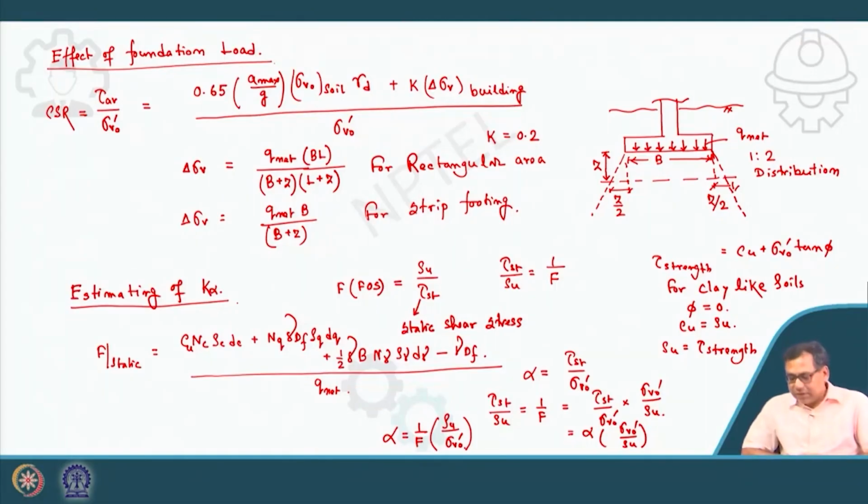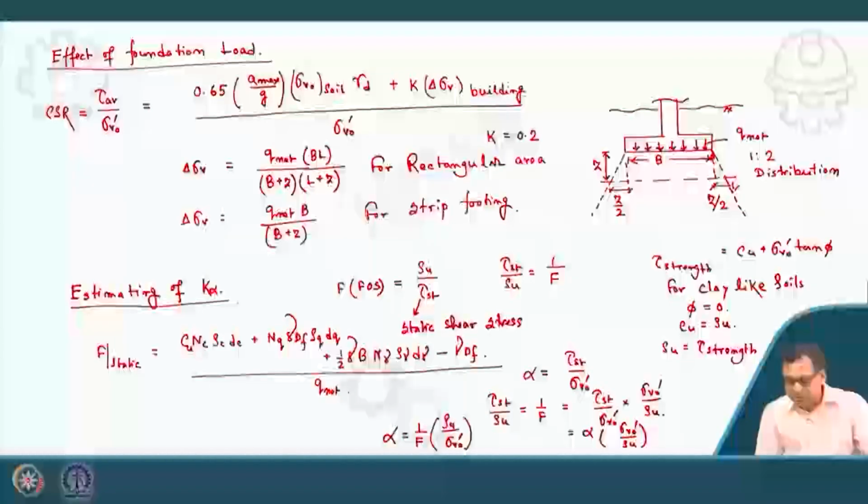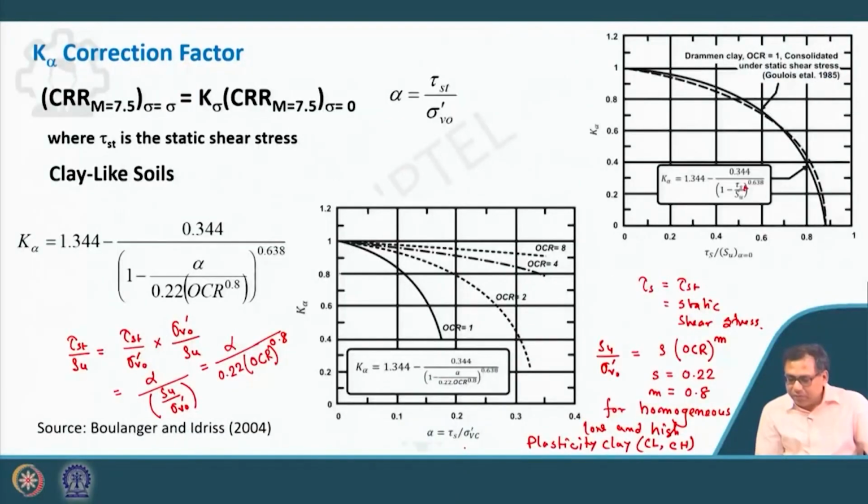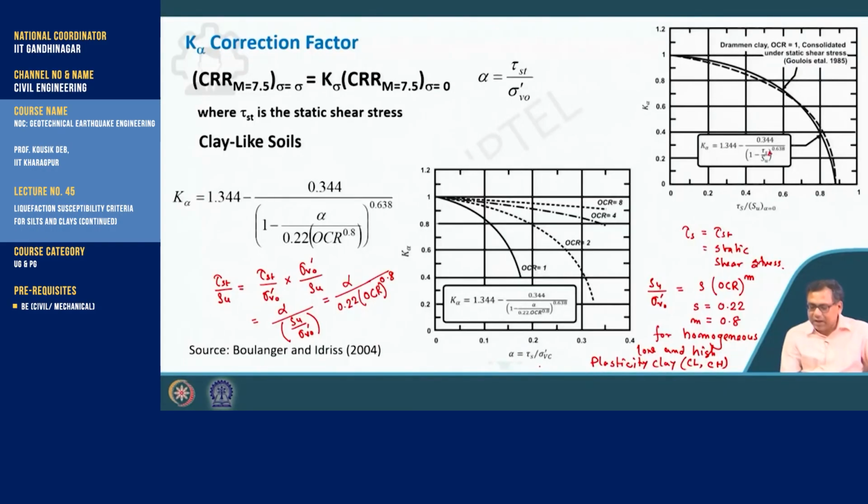So this way I can calculate the alpha also. Okay, but here the alpha calculation for normally consolidated clay is not required. For over consolidated clay, yeah, alpha calculation is required here.